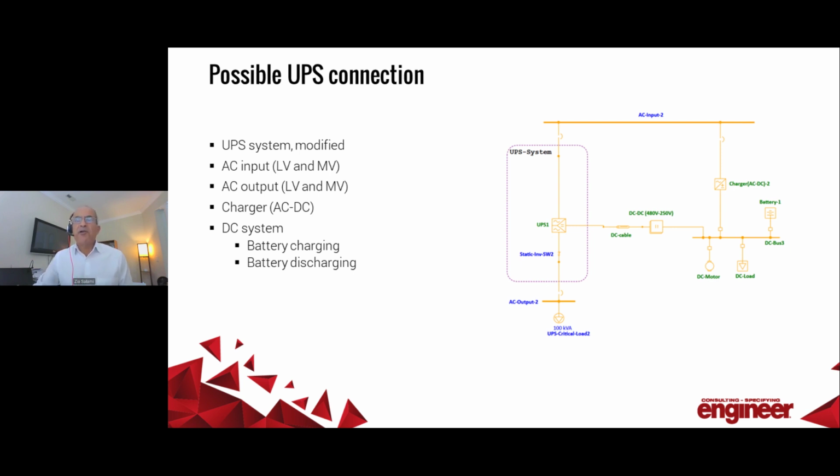I will discuss several of these parameters that we covered in the video clip in later slides. Now, the second possible UPS connection that I want to point out is mainly when we have a larger facility with additional DC loads. We can have a charger in parallel in addition to the UPS system to perform redundant charging of the battery at the same time, either from the UPS or from the charger, and at the same time we have